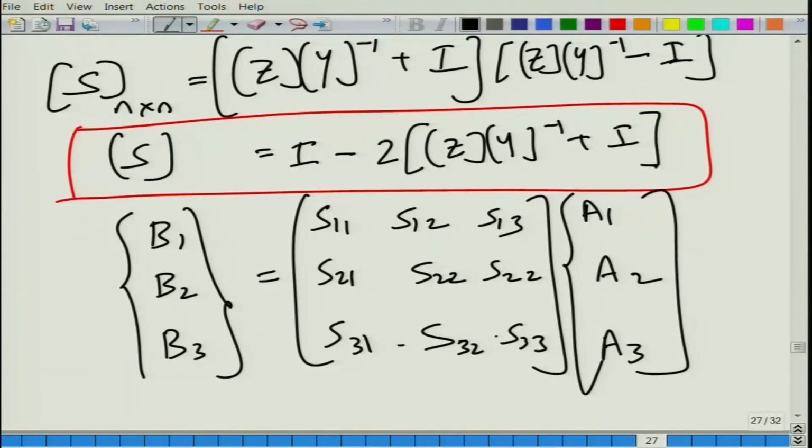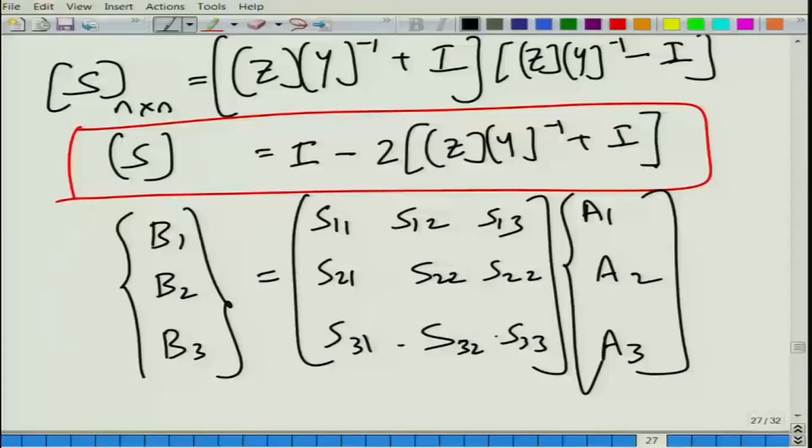Now, let us first analyze a single inlet and single outlet system in terms of scattering matrix. Impedance matrix, we will be characterizing a single inlet and multiple outlet, a single inlet and single outlet rectangular chambers or circular chambers in terms of circular functions or Bessel functions, whatever the case may be. But we will also analyze a muffler with 3 ports.